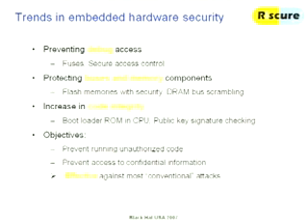If you look at chipsets that implement all these features and build a system with that, and you at least do the design properly, you actually end up with a system that's pretty well protected against what I would call the conventional attacks. The attacks that you can do with a couple of $100 in equipment, like scraping off glue, soldering iron, flash chip reader, those kinds of attacks.